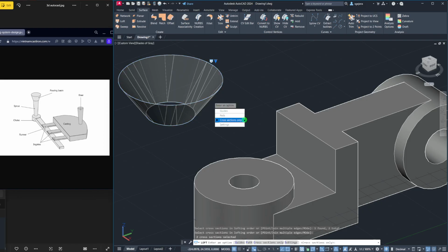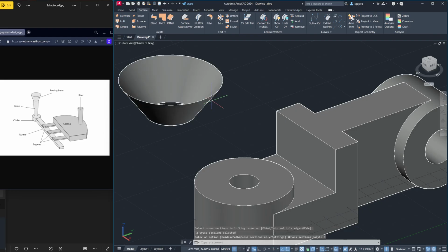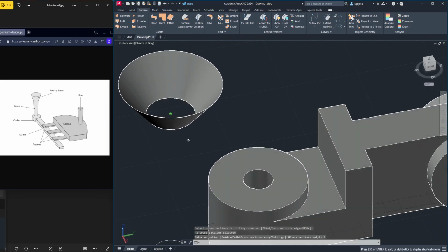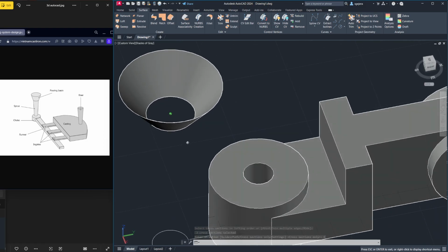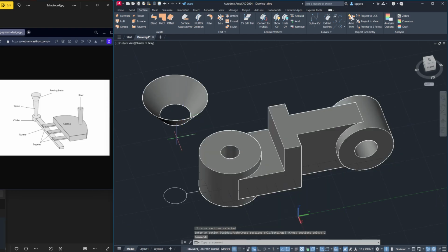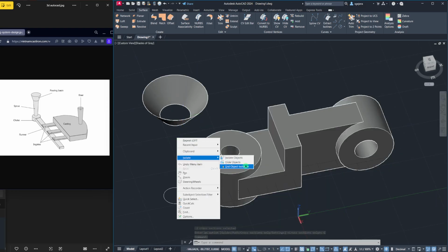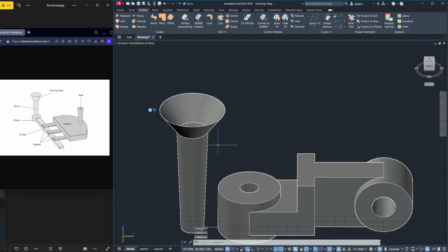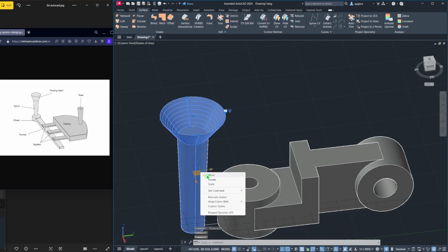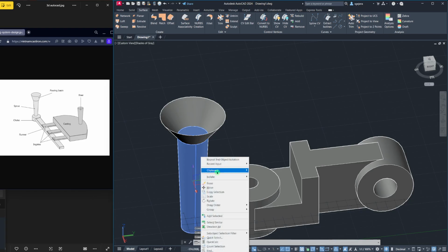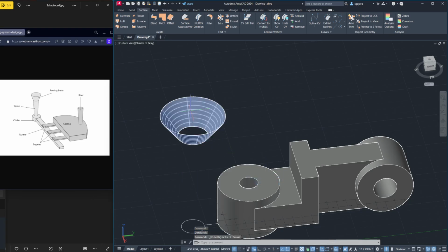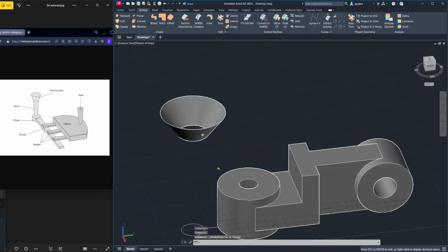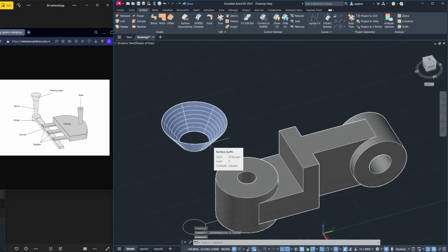Parang ganyan. So, let's do cross sections only. So, it creates a loft like this. Tapos, ang problem dito is, hindi siya solid. If you end object isolation, para siyang surface actually. This is a surface, and when you export this as a surface, hindi siya mag-act like a surface. So, kailangan natin gawin is, we need to close this surface. Kailangan natin close tong surface na to, and we call it a watertight enclosure, para pag watertight siya, pwede na siya ma-convert into a volume.